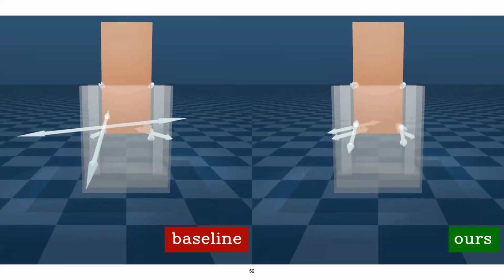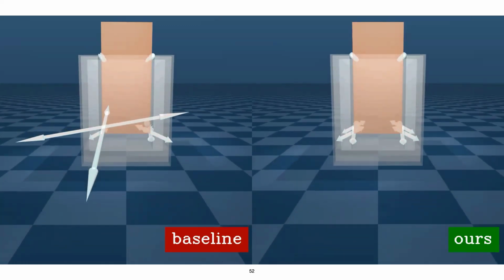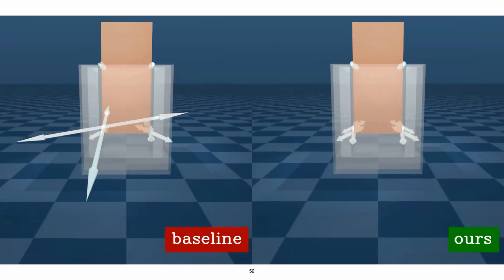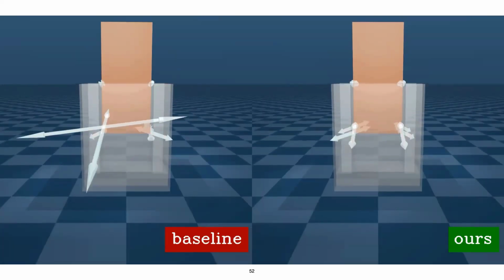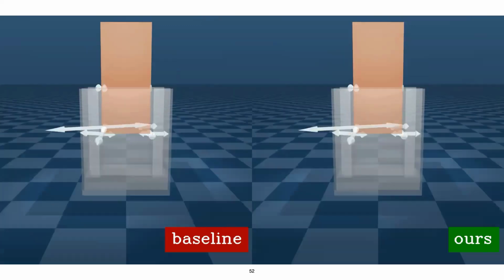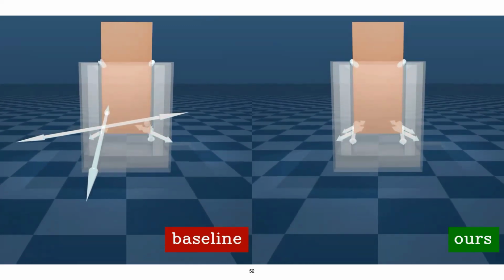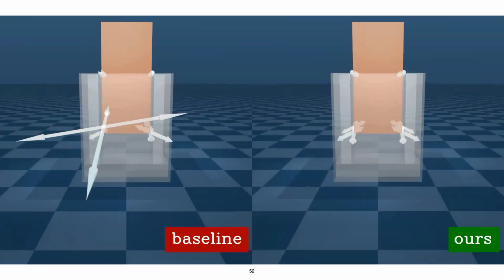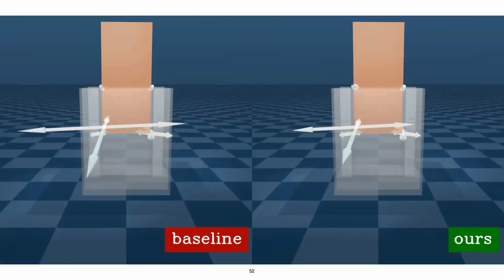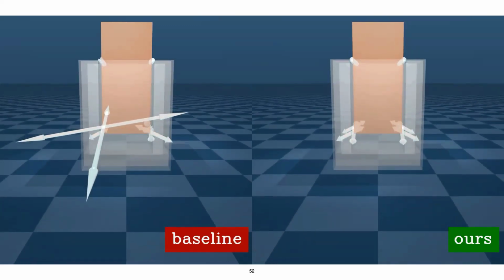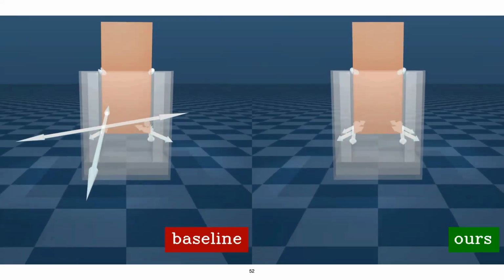So here on the left, I have a plug that is slightly misaligned, and the instruction is just to shove. As we shove, we see these contact forces are relatively large and they're super misaligned. Now, alternatively, if we do a little bit of wiggling and we learn this mapping between what our control is and what the force torque on the plug is, we can learn this very quickly, and then we can use this linear mapping to effectively remove all of the unnecessary contact force on the plug itself.